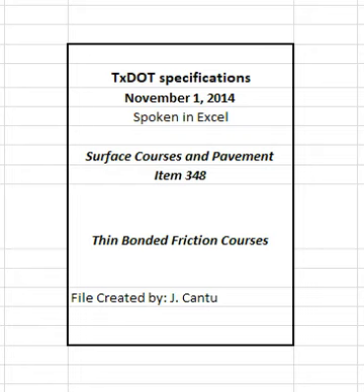Ensure the paver does not support the weight of any portion of hauling equipment other than the connection. Provide loading equipment that does not transmit vibrations or other motions to the paver that adversely affects the finished pavement quality. Equip the paver with an automatic dual longitudinal grade control system and an automatic transverse grade control system.